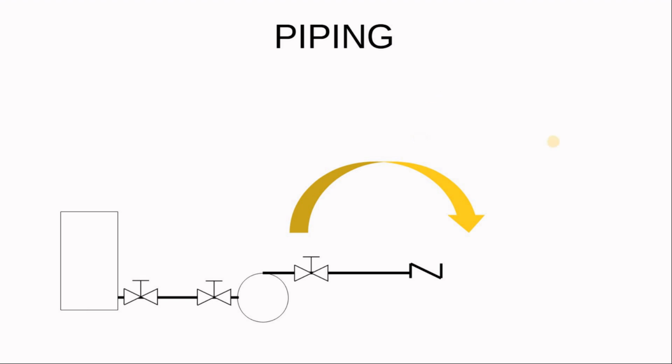So you can see here you have isolation valves, so you can isolate your pump, suction and discharge valve. If you close both of them, you can maintain, change, do all the maintenance you need for this pump. This non-return valve, if you move it in this area, meaning moving this valve downstream of the check valve, you can also maintain the valve by closing the discharge valve and the suction.